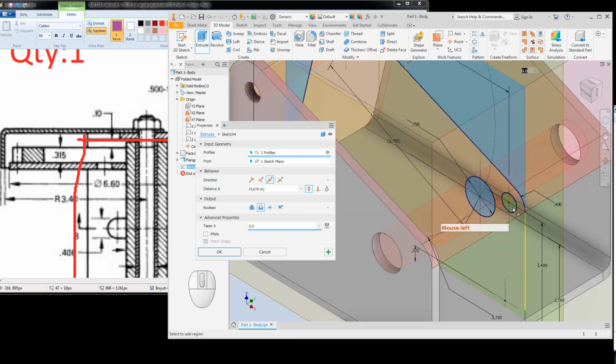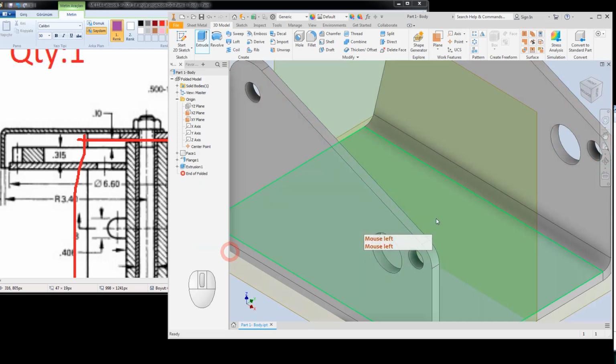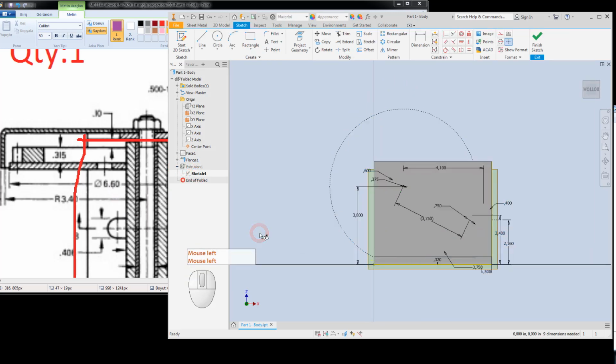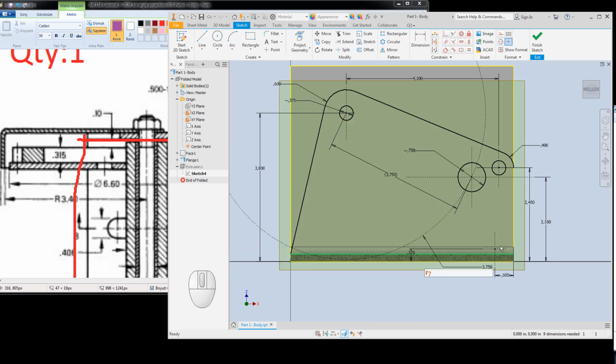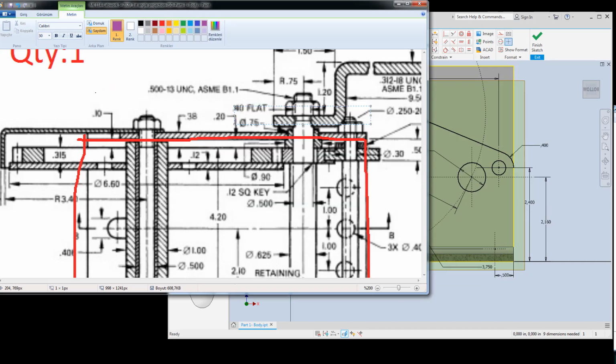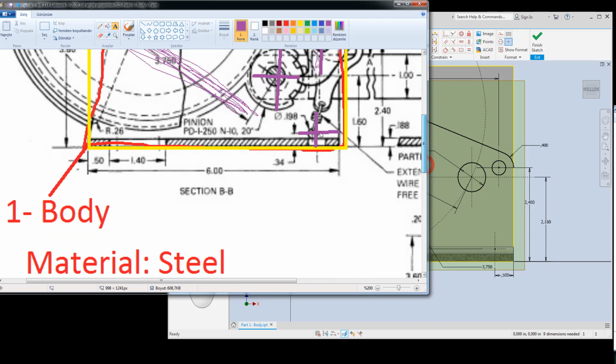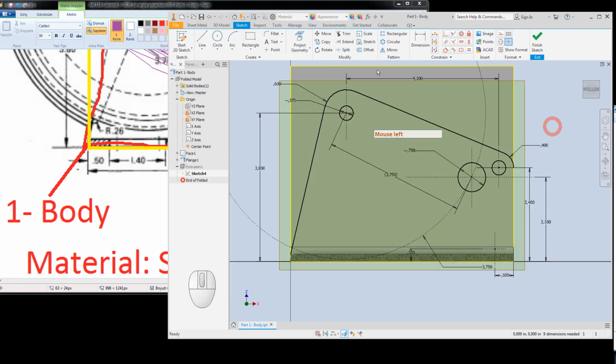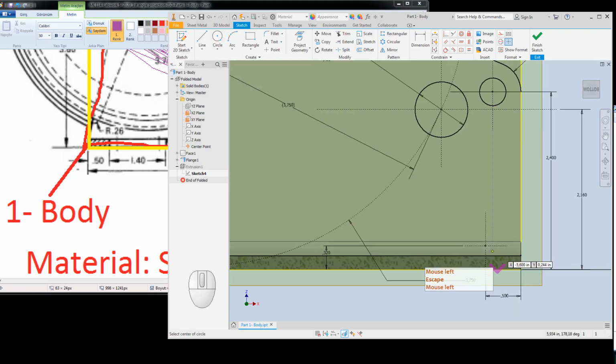and this one. Also I have forgotten one hole here, and again I will add that hole with F7 tool, which is this one. I have forgotten the spring holding tool, which is this diameter is 0.198. Again I go to this point, I add the dimension here, which is 0.198.